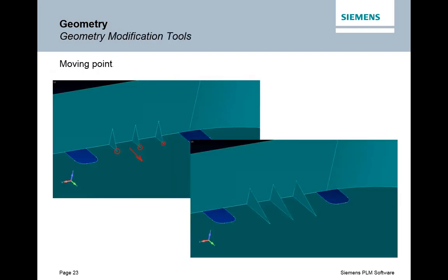Next, another big improvement: you can change the shape of a surface simply by moving the points along the edges. So in this example, these three little gusset features have their surfaces changed just by moving the points that describe that surface. If we wanted to run a quick comparison of before and after with the structural behavior of these gussets, with the dimensions they had before in the upper left versus lower right, it's really easy to do because we'll be able to just pull those points and modify those surfaces directly. It's just not something you could do before in Femap.